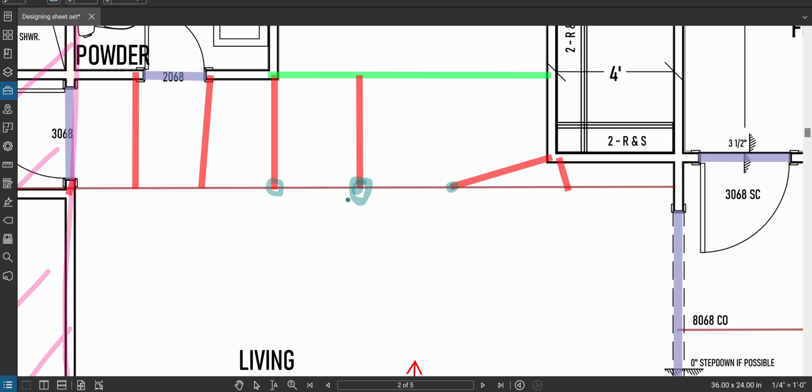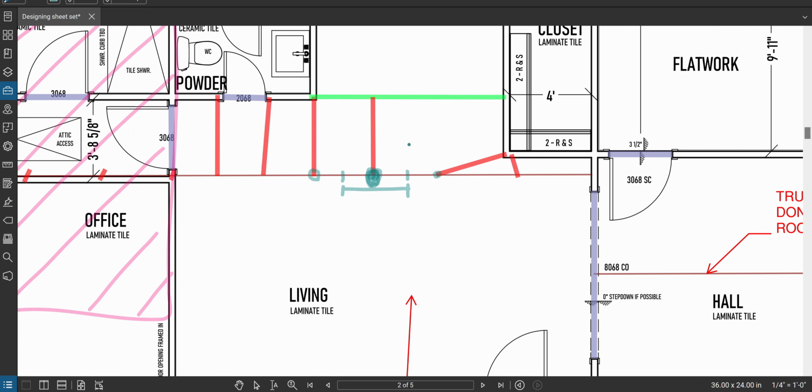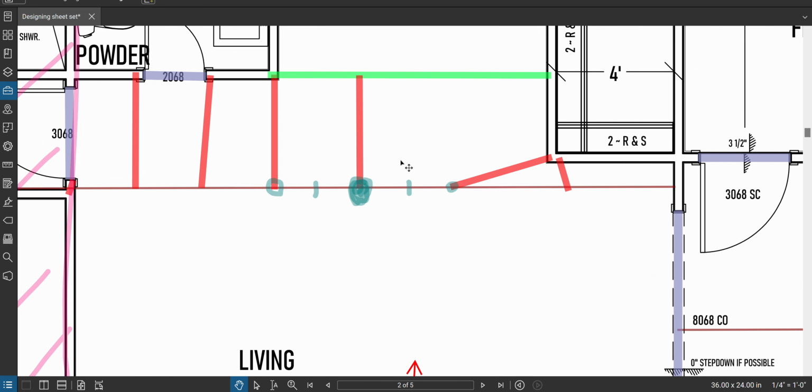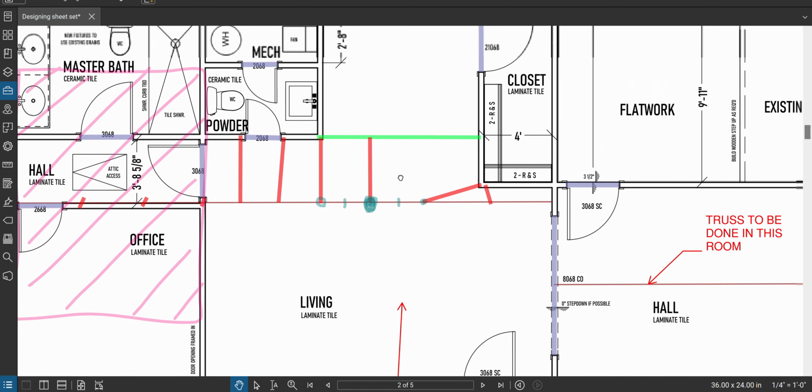So how much roof ridge am I responsible for, because of tributary areas, from this center support here? I'm going to go halfway to this one, boom. And I'm going to go halfway to this one, boom. I'm responsible for holding this width of the ridge. Cool? Cool. The rest of the width is going to go over to that brace and then down to somewhere else. So I got that width. That's my width that I'm responsible for. Take that line. Okay. Now that gives me one dimension.